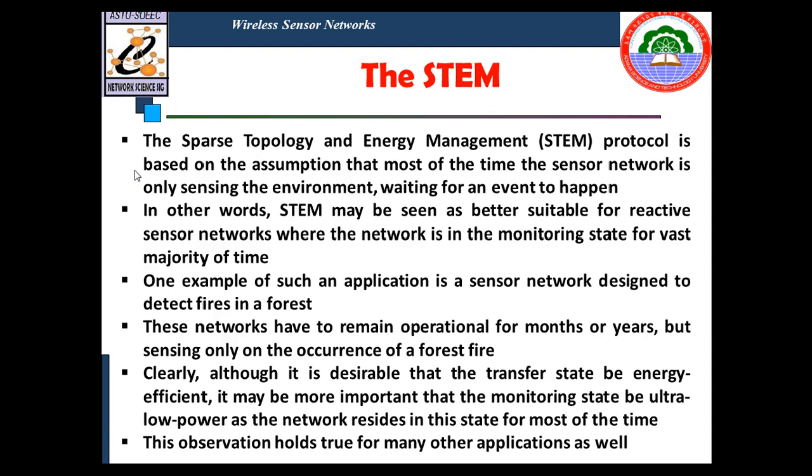If the packets need to be relayed further, the target sensor node will become the initiator node for the next hop and the process is repeated. Once both the nodes that make up the link have their radios on, the link is active and can be used for subsequent packets. However, the actual data transmission may still interfere with the wake-up protocol. To overcome this problem, STEM proposes that the wake-up protocol and the data transmission employ different frequency bands. In addition, separate radios would be needed for each of these bands.